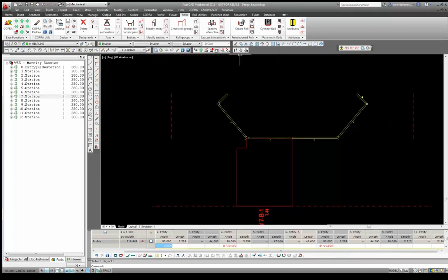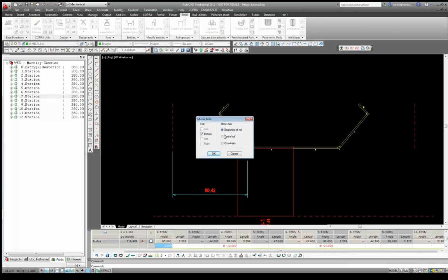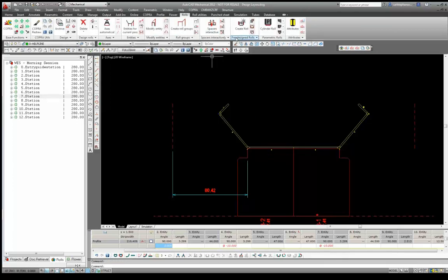Save the pass, and now I can take a quick look here on how things could look for my side roll. Okay, so clearly I would have a 160 diameter roll here. Going to increase that slightly. So now I will go axes left and right. But I need some construction over here on the right hand side. So again, mirror roll groups, tool, the bottom, end, OK. And again, join these bottom rolls. And I have some construction now for my side roll axes.